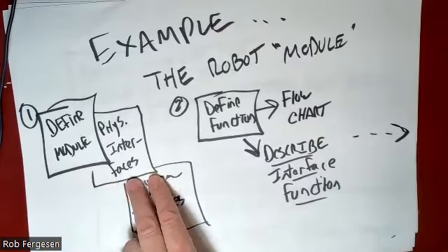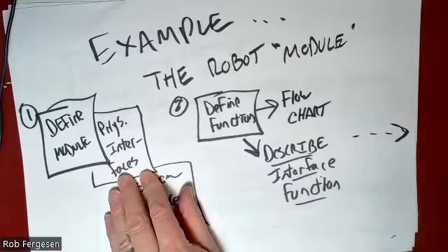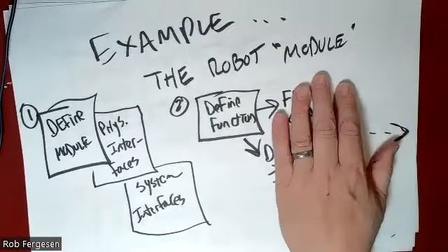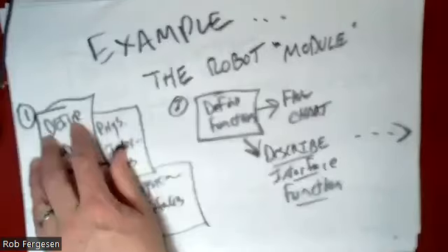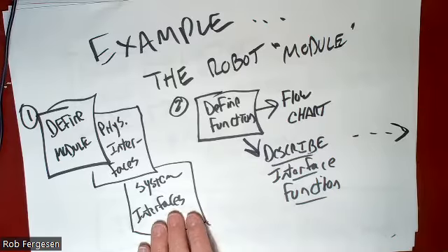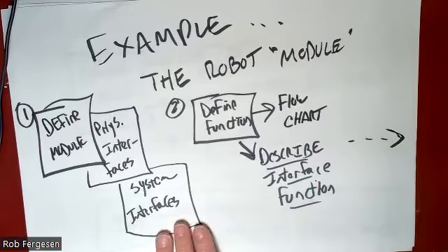For that robot, you define the physical interfaces. So what's a physical interface? It's when the robot pushes a button by the robot actually pushing the button with the gripper. There might be a number of physical interfaces. The robot's the only example of a module that will get a physical interface. In every other module, you're going to have system interfaces. In the case of a robot, we've got I/O. And so our I/O list is the system interfaces, the inputs and outputs associated with what's going to communicate to that robot.